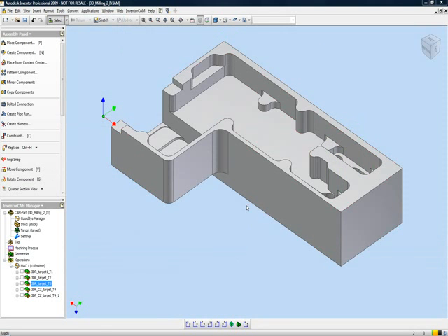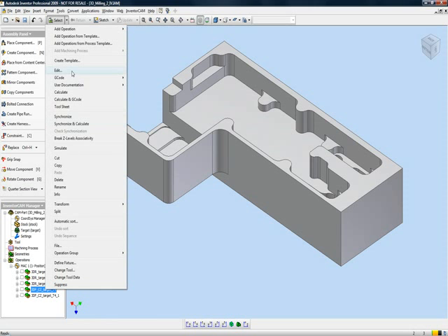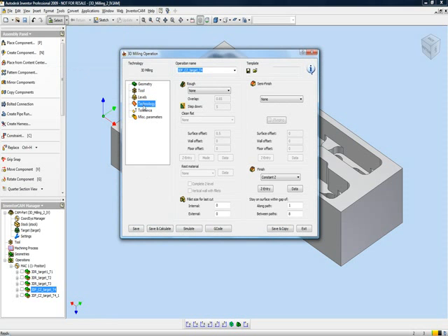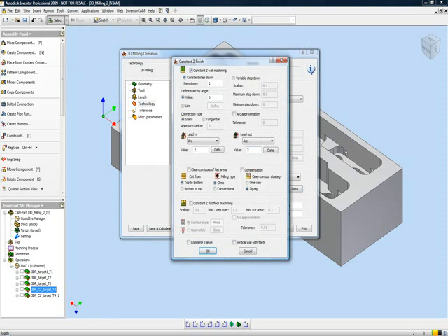Now in my next operation, I'd actually like to start machining and finishing the walls itself, and after that also the floors. So in the next operation, I've chosen again my target, and the tool I'll be using will be a 4mm end mill, and in my technology I'll be using the option of constant Z, going down every millimeter on the wall itself with a lead in and a lead out of an arc of 2 millimeters. If I were to do the simulation,